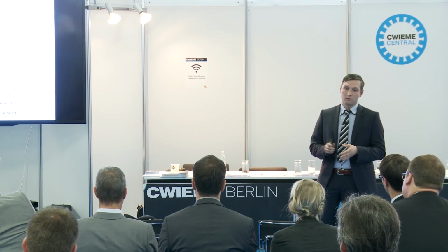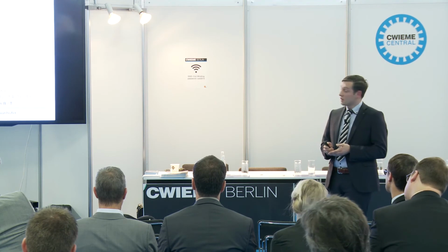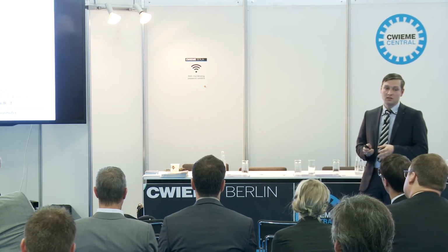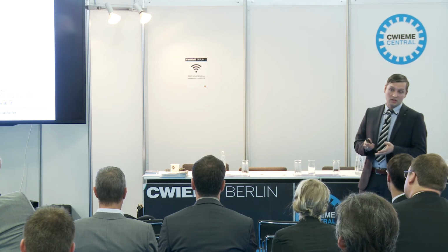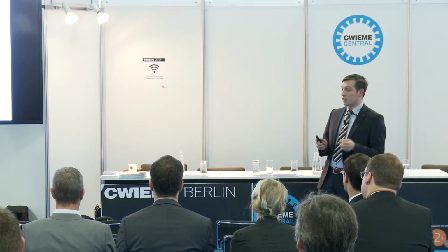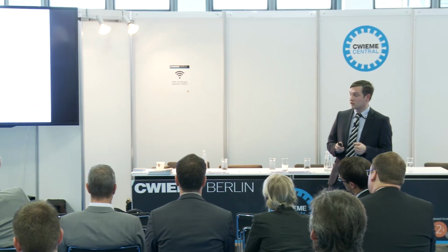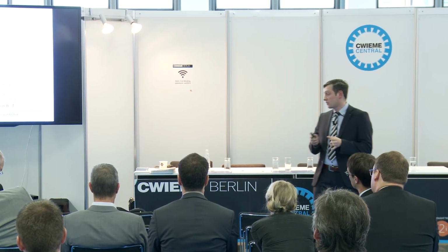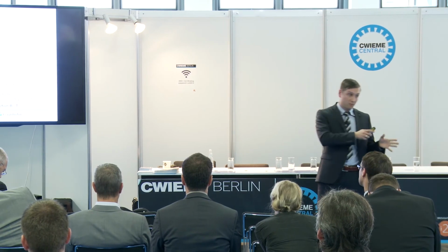So now let me conclude a few points from that presentation. Today, I showed you a cutting technique that is 2 times faster than conventional laser fusion cutting. It's a very flexible technology in terms of material grades, gauges, as well as you can adjust your process between perfect magnetic properties or output.